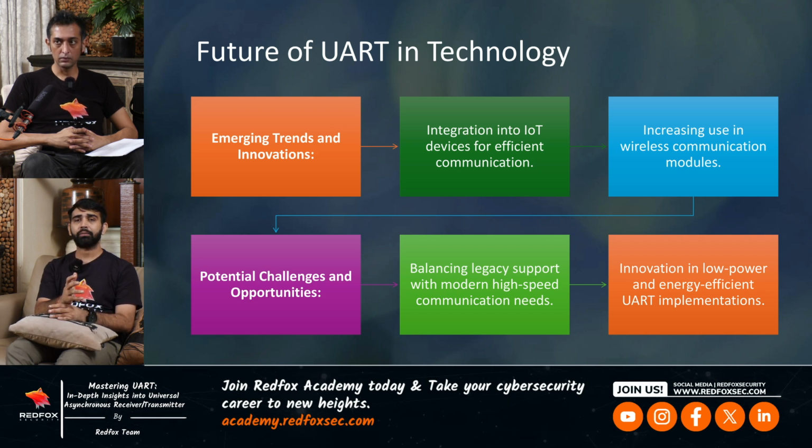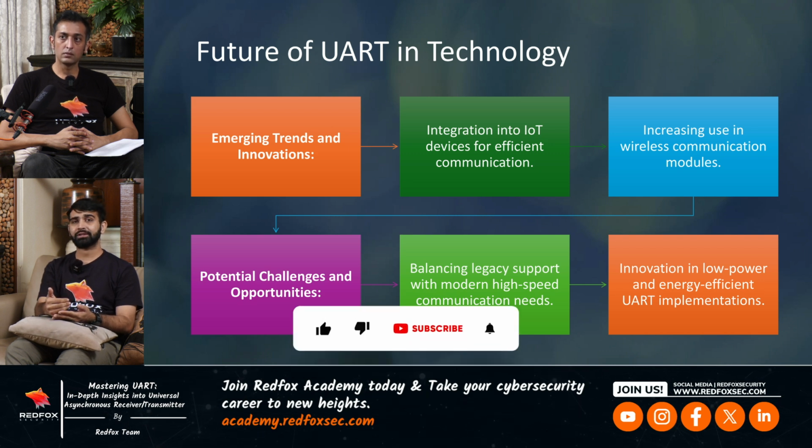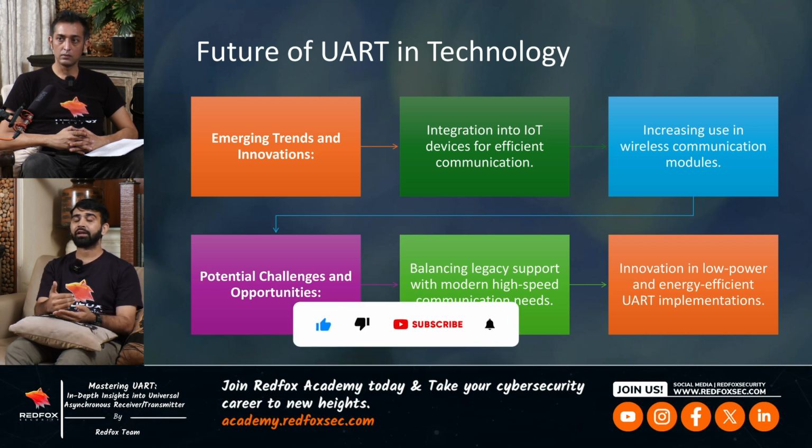Then consumers and attackers, whether researchers, ethical or non-ethical, will not have access to the boot terminal, kernel terminal, or firmware. If the UART is not disabled, they can interact with the live firmware; if it is disabled, they can't.